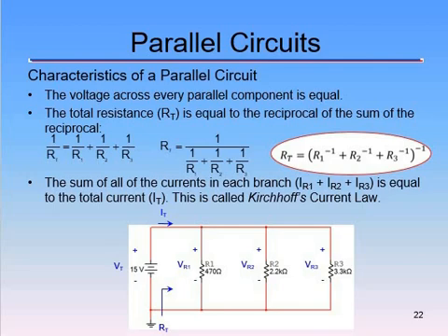These guys are relatively just as easy as series circuits, but everybody commonly mistakes them back and forth. So please understand, when we do parallel circuits, the biggest thing that really changes for everybody is remembering how to calculate parallel resistance. The characteristics we talked about before: this time there are multiple branches for current to flow through. There's a branch through R1, a branch through R2, and a branch through R3. We call those branch currents.